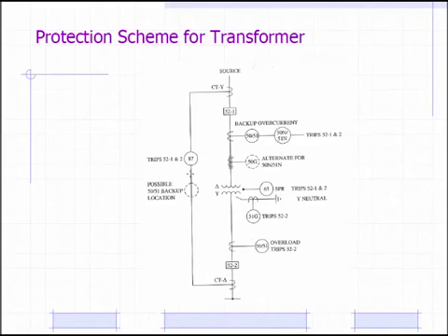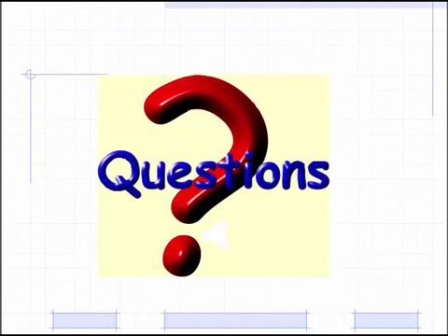And this 87, if you looked up 87, it would be called a differential relay, and what it's doing, it's comparing the power going into the transformer to the power coming out, and they should be the same, very close to being the same. If not, then there's something wrong and they trip. We're going to do a lot with substations in the next few weeks.